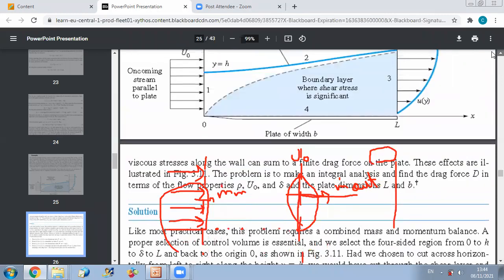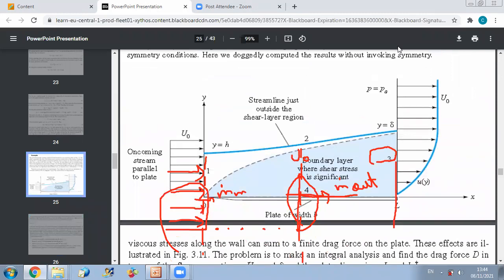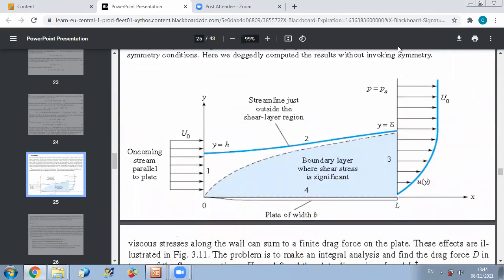Please, in such problems, always think of applying both the continuity equation and the linear momentum equation. These are the two main applications of the Reynolds transport theorem we have covered until now, and this is the application that you are responsible for in this exam. So you should always think about combining both, because to calculate a force, you need to know the velocity profiles. What you are interested in is the total drag force exerted by the wall on your fluid.